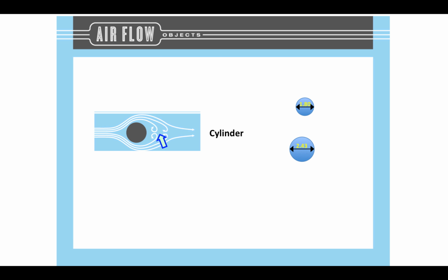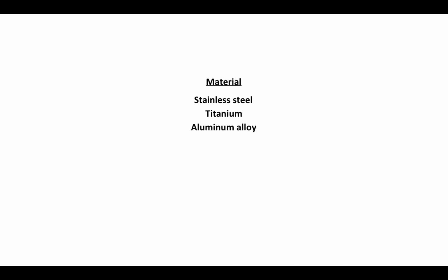And looking at it again from the standpoint of aerodynamics, I'm obviously better off once again with the stainless steel spoke than the somewhat thicker titanium spoke. And for the reasons we've seen here and many others besides, this is why it is overwhelmingly better to use stainless steel in the wheels of most bicycles. It's absolutely a fantastic metal for that purpose and unequaled by any other.